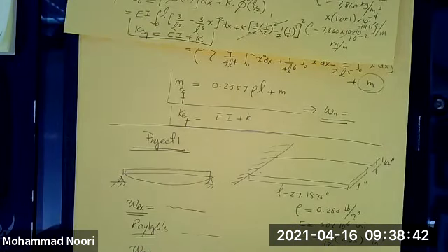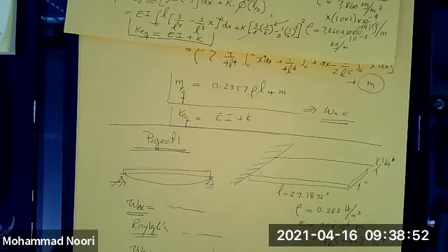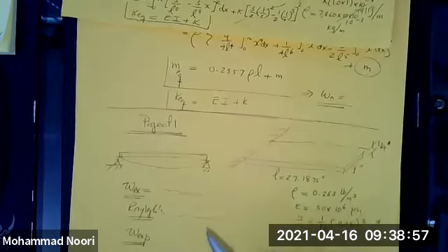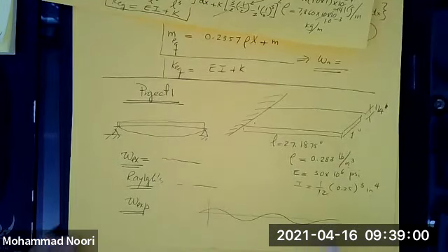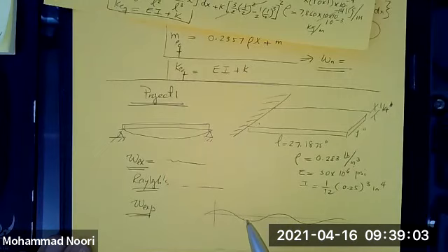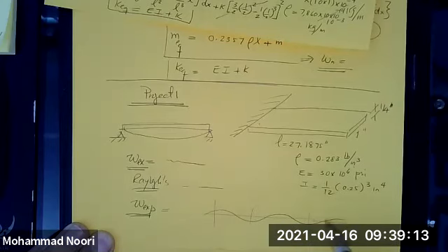But anyway, you vibrate it, and you can use the video recorder on your phone or whatever and measure the cycles per second. So theoretically speaking, this is an undamped system. So when you vibrate that, this is going to be the response, right? If you measure the cycles per second, convert that to radians per second or hertz, you can find the natural frequency, peak to peak measurement in one cycle.